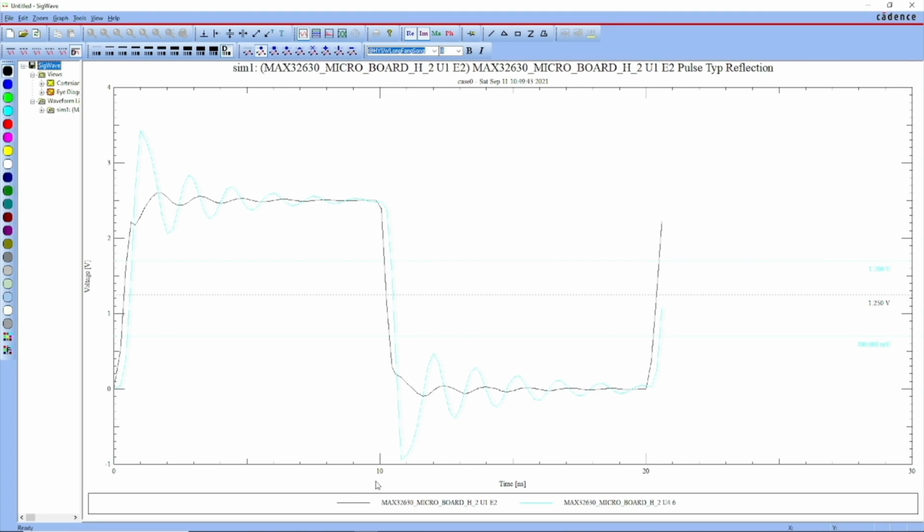So since we do have some reflections, which can cause ringing on the signal trace, it will carry the voltage signals we want. However, it can cause some EMI issues if not contained. To deal with these kinds of issues, I've developed a certain methodology that I call DEPSI. DEPSI is short for Design for Manufacturing, EMI, Power integrity, and signal integrity. These are the four major pillars I use to base all foundational PCB design learning, education, knowledge, and review, solving any kind of issue on a printed circuit board.